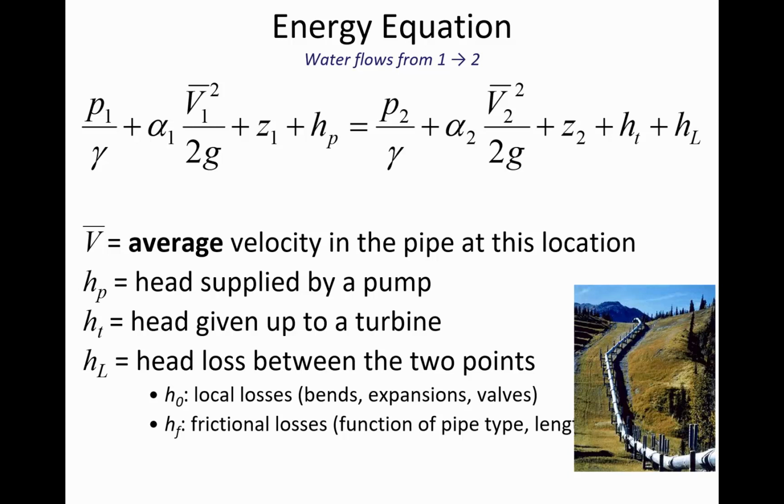Like if there is water flowing through some sort of a valve, then the turbulence that the water experiences as it flows through that valve, if it has to change direction, or if the valve is a gate valve and there's a lip inside of that gate valve, or it's only partly open, there's going to be some energy loss as the water goes through that transition. And that localized decrease in pressure we account for here with H sub L. And then the frictional losses that are distributed, meaning it's over an entire length of pipe, that's H sub F.